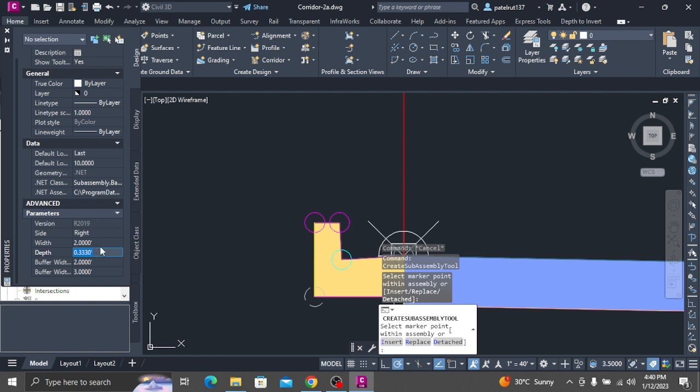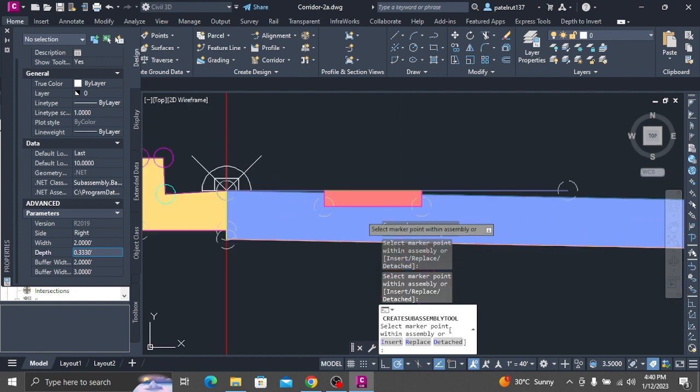In the Transition Profile row for Basic Lane Transition, right-click the Object Name field. In the Set Slope or Elevation Target dialog box, specify the following parameters. Select Object Type to Target, Profiles. Select an Alignment, right, 1. Select Profiles, Layout, 1. Click Add. Click OK. The right side edge of pavement elevation is set to the Layout, 1, Profile.